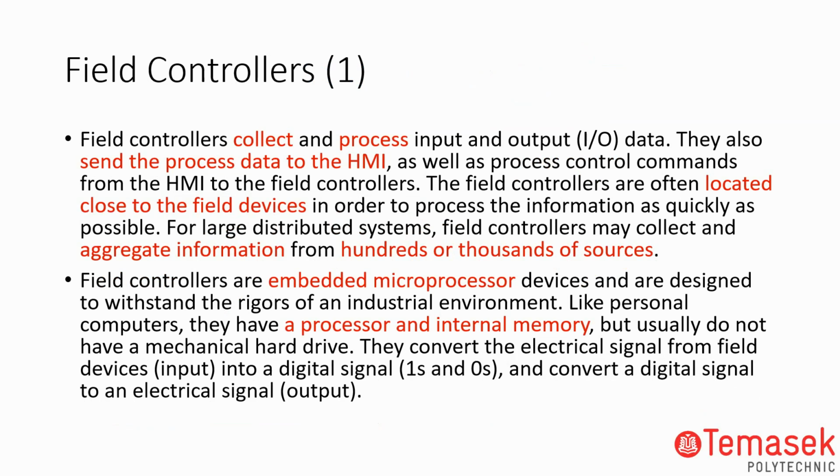Next thing is the field controller. The field controller collects data, processes data, and sends information to whatever the field devices are doing. It's close to the field devices, so it collects and processes inputs, and then also sends data to outputs, and whatever is completed, it will also feed back to the HMI.